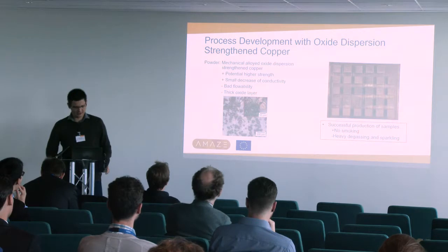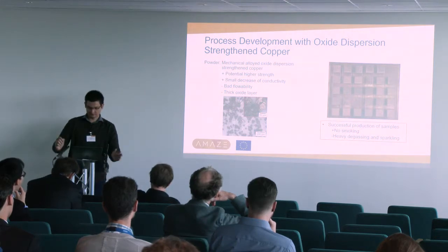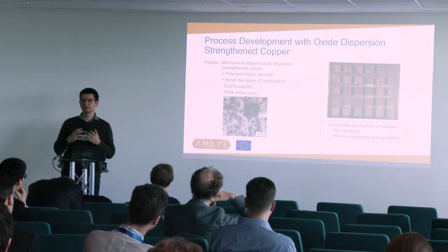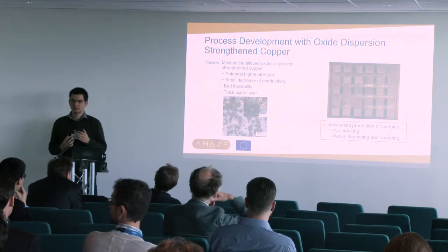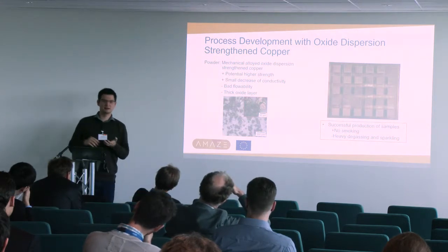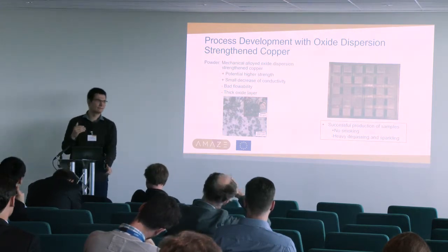So then we started, and we built it. We managed to build successful samples. We had no powder blow up, and even though the process looks very unstable for those familiar with electron beam melting, it looked something like laser beam melting. We always call it at our chair a moving volcano when you look at the laser. In electron beam melting, we are not in the keyhole regime, but only in diffusion. So we are welding through thermal diffusion. Normally we have no volcano, but with this alloy we had it.